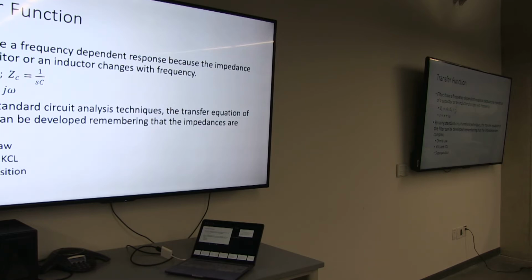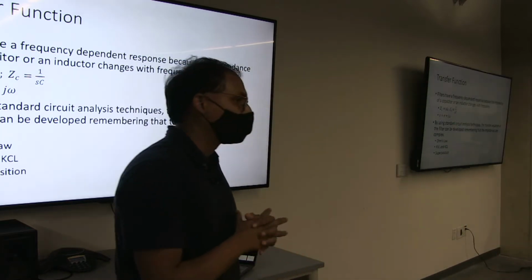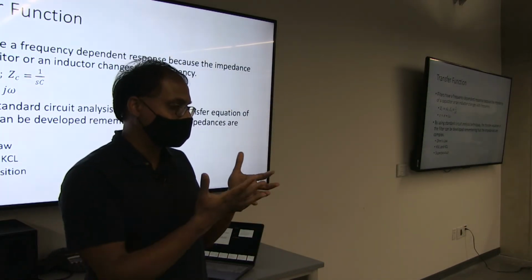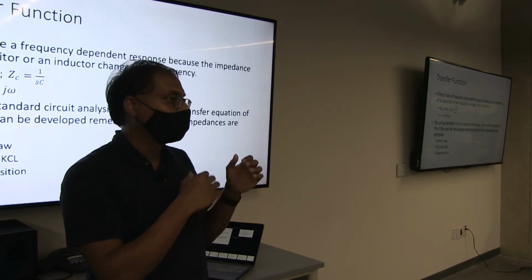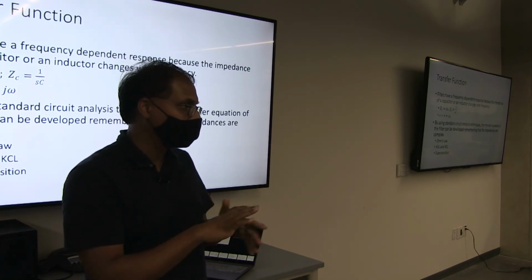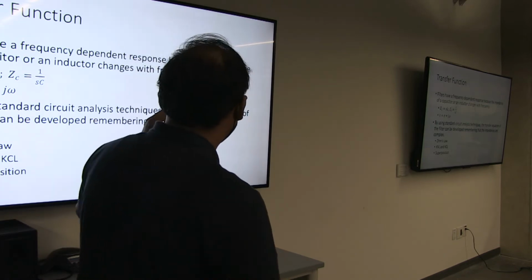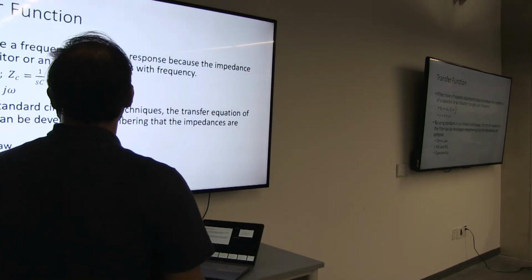So the question is, if we have different filters with different group delays? Correct, that's correct. So we've looked at normalizing the curves to understand how the filter behaves. We have looked at amplitude response, phase response, and group delay. And let's take a quick view at transfer functions.